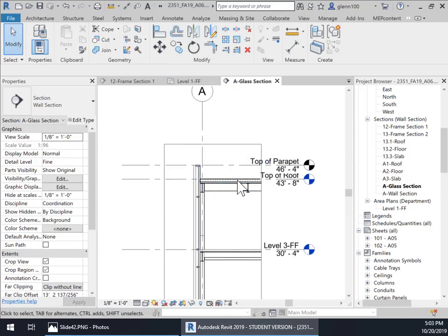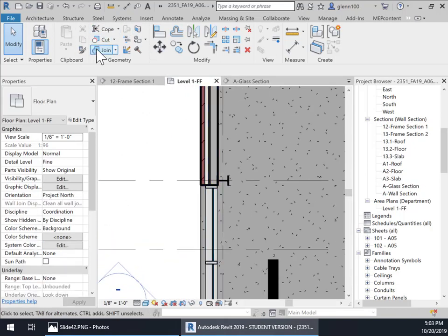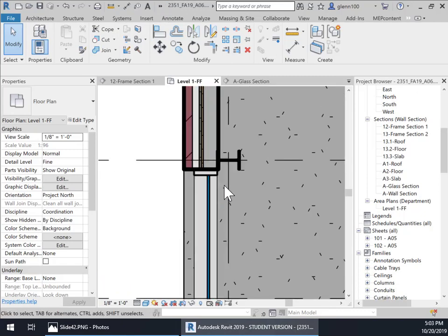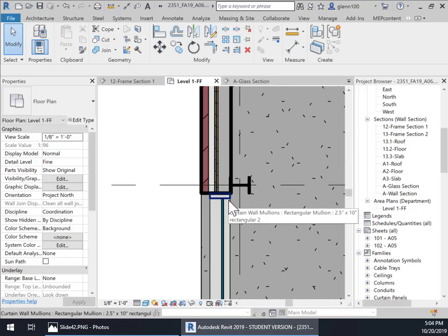The next thing I'm going to do to kind of correct some of this is, now that I've got this aligned, I'm going to go back to my first level here, and notice I've got the thick lines on. These are proportional. They're not exactly the thickness that the lines are going to be when they plot, but they're showing you that different lines are going to be plotted at different widths, okay?